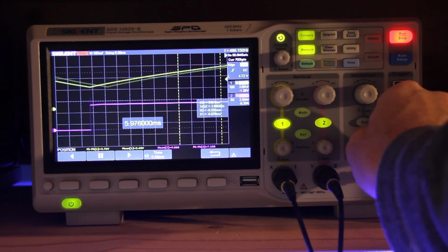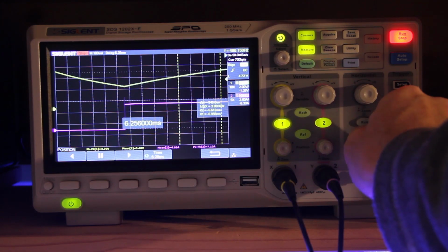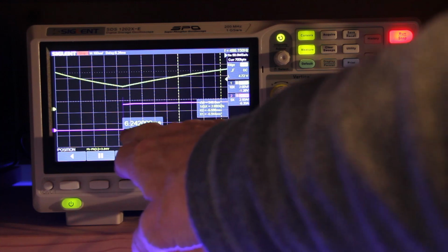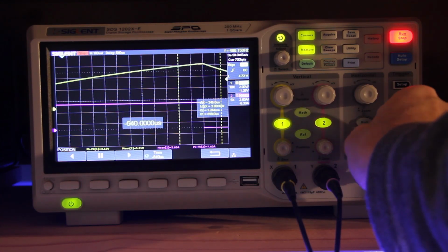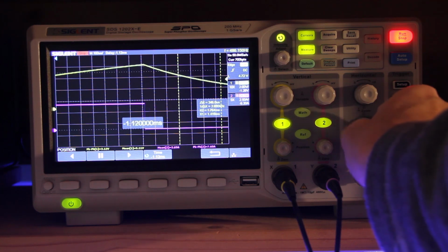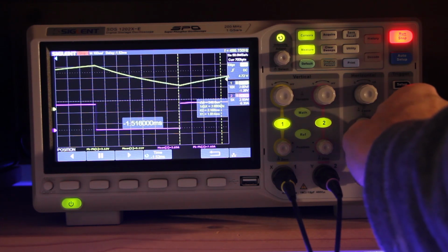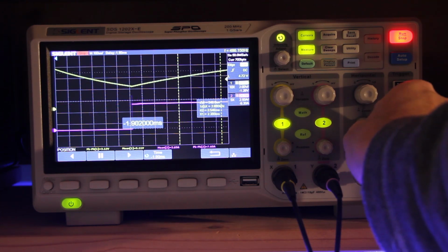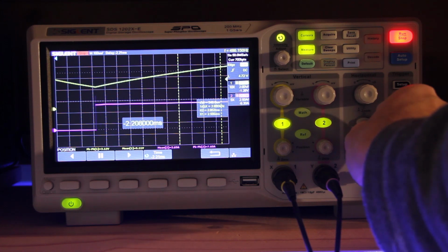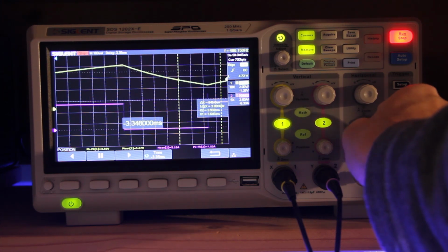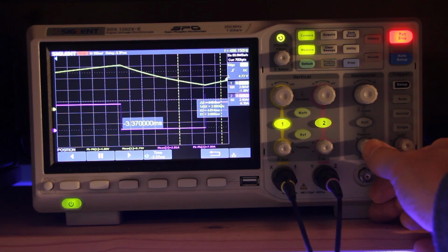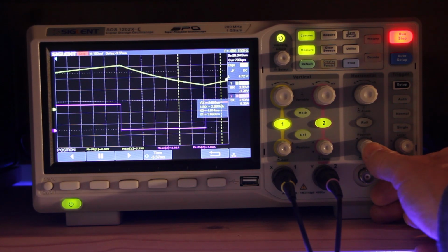For example, we are here at 6.2 milliseconds before the event. This is because the instrument has a continuous circular memory, and the trigger happens at the middle of this memory size. The indication is the time position. On certain instruments, this is indicated as delay. Therefore, negative numbers refer to the history before the trigger and not after, as in this case.